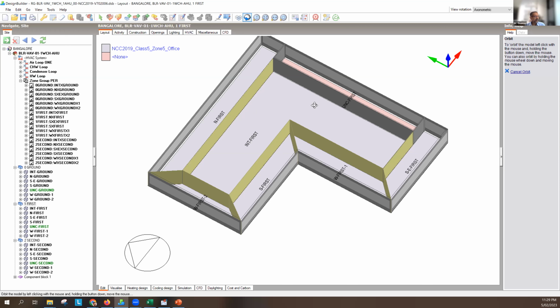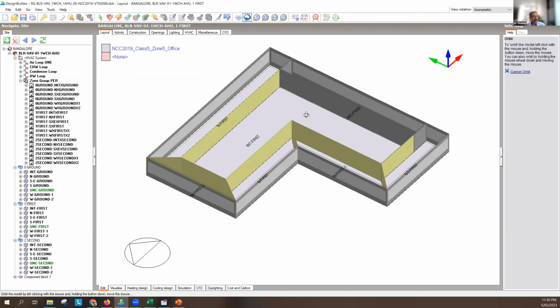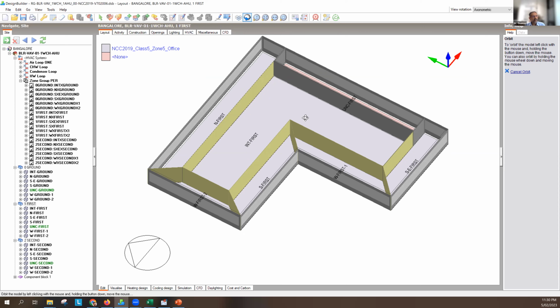So one of the things I might do is to first put the internal zones in a different AHU. And there I can then start to give it less cold air and control it differently. And then you will find that the energy use may come down, again for pumps, may not be for fans. So those kind of options can be explored, where delivering the best outcome from your HVAC plant and system needs to be thought about.